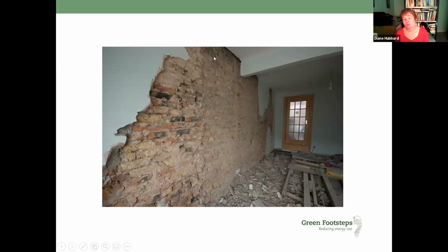So what we want to do, if you're thinking about air tightness on your home, is start thinking about the places where this plaster is not continuous or where it's broken. So things like what's happening at the skirting board. You know, skirting boards are there to sort of disguise the plaster stopping short of the floor.